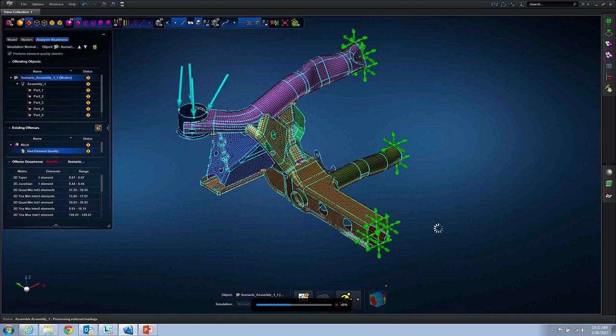And in this case, since it's going to be modal analysis, it's going to extract the eigenvector for the entire assembly. This time it's going to take about 40 or 45 seconds to regenerate those model results, and it should be ready in just about 10-15 seconds. And like I repeat, in the computational parts based system, what we do is create computational parts, assemble, solve, and recover the results. And right now we recover the results for modal analysis.